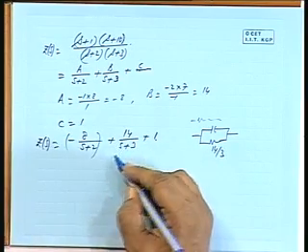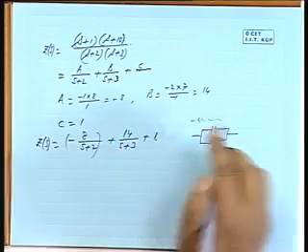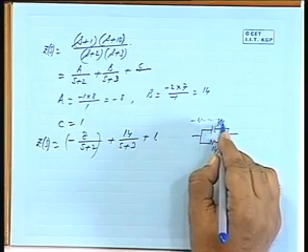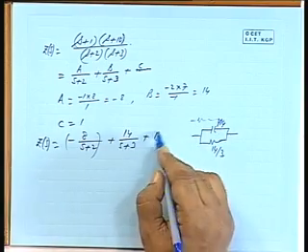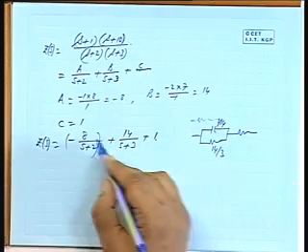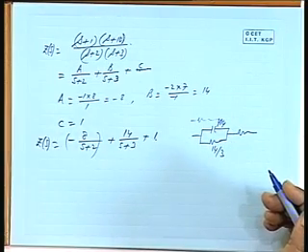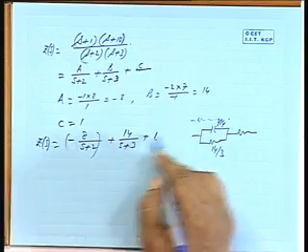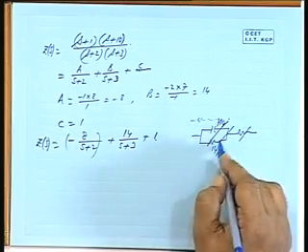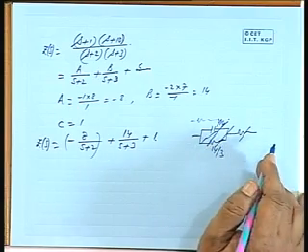Make S tending to infinity, it is 14 by S, that means 1 by 14 farad. So, this is an RC combination. This is a 1 ohm resistance, but I cannot realize minus 8 by S plus 2. It is not possible to realize by RC elements. So, I would like to know whether it is possible to realize this.